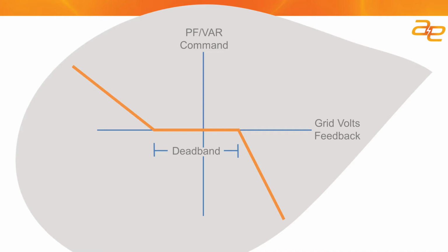leave it alone. But if it goes above 120 or below 116 kV, then we want to either buck grid voltage or boost grid voltage with some VAR support. The VAR support will always come in the form of VARs, but it could be commanded based on one of 3 things. Either PI or PID control, where we're just trying to inject enough VARs to get back to set point, and that proportional integral math over time gives us a nonlinear response to the deviation.